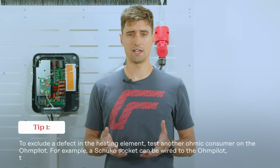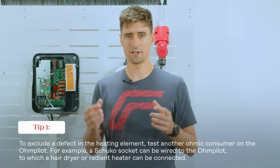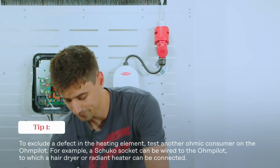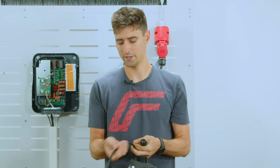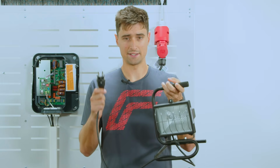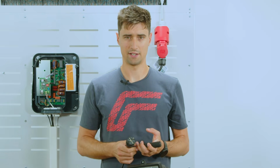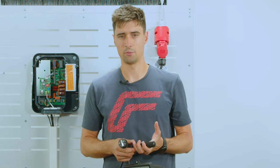First of all, if you have the material, why not build by yourself a power socket that you can connect to the Ohmpilot, and where you can connect a different ohmic load to the Ohmpilot. In our lab, we do have this guy here, and if you connect the power socket to the Ohmpilot, you can connect this floodlight to the power socket, and if this one is running and the heat element is not running, then very likely the heating source has a failure. So in that way you can check very quickly and you see if the Ohmpilot is working or not.